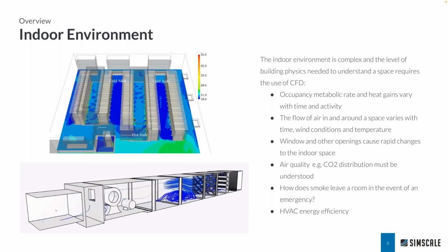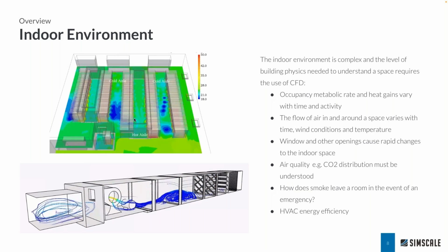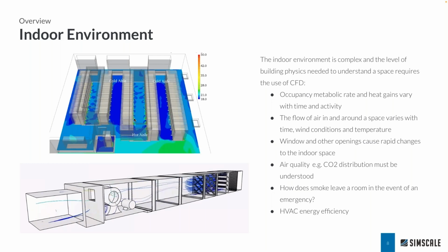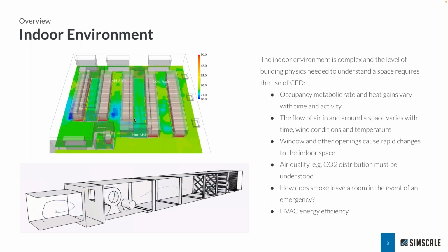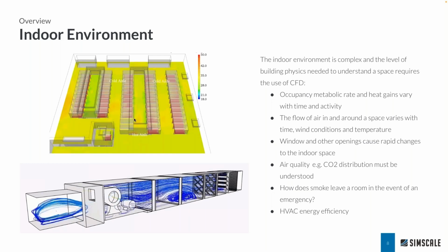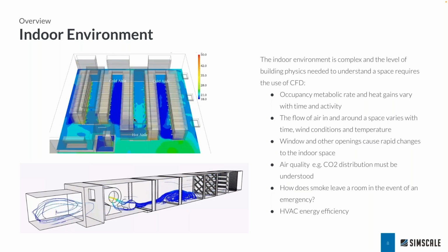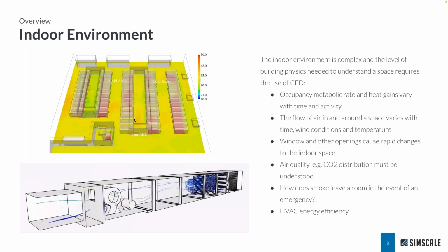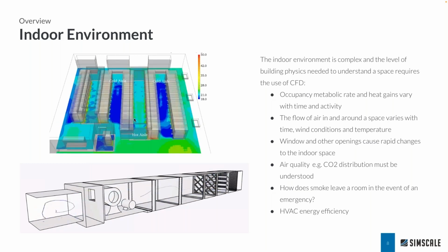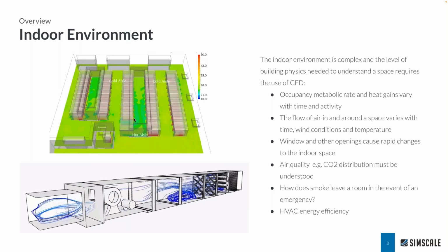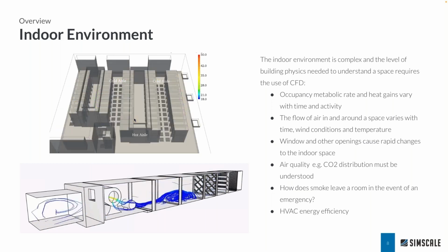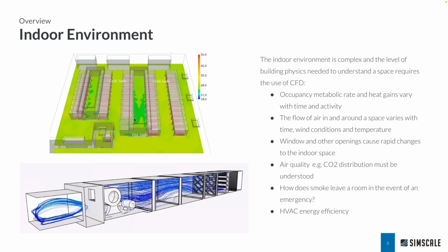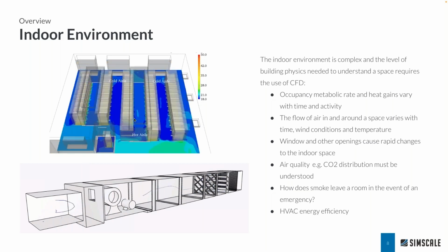And if you take the other side, if you have a restaurant, then you need to make sure you're designing the restaurant to be suitable for the particular number of occupants that's going to be there. It can be the worst case scenario where you can have a lot of occupants at a time. And the other time, you might need to actually optimize the HVAC system so that you're not oversizing when there are no occupants or when there are fewer occupants. So these kinds of really interesting insights are important to design a perfectly comfortable indoor space.